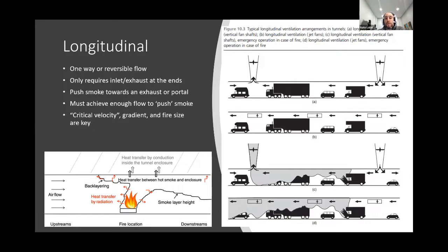And then we have longitudinal exhaust, which we do call exhaust, but some engineers, the first time they say it, won't really think of it as exhaust, because really it's pushing. Effectively, it's what it sounds like. Longitudinal is you try to push all the smoke one direction.